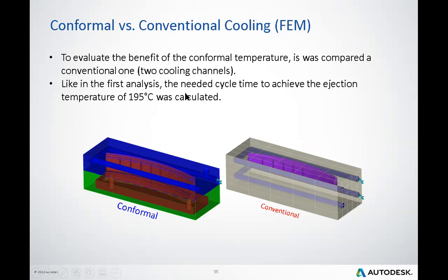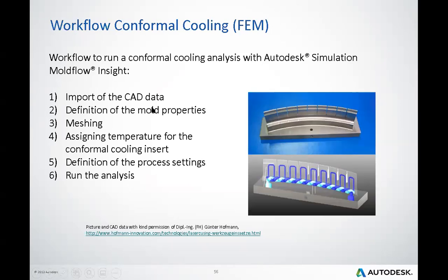Like in the first analysis, the cycle time needed to achieve the injection temperature of 195 degrees centigrade was calculated. So this is the condition. The workflow that we're going to follow, the first step, is import of the CAD data. If we don't have the 3D CAD data, we cannot go into Moldflow anyway. If we want to use this technique, we have to have 3D CAD first.